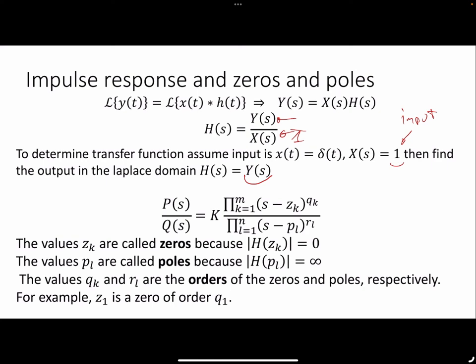What else is there? So yeah, you should know that these are called zeros. These are poles. And you should be able to infer the order of a pole or a zero based on looking at your frequency response graphs. And you should be able to infer stability based on the location of the poles. So remember, a pole that has either a 0 real part or a positive real part leads to an unstable system. Either 0 or positive, unstable. Negative is stable.